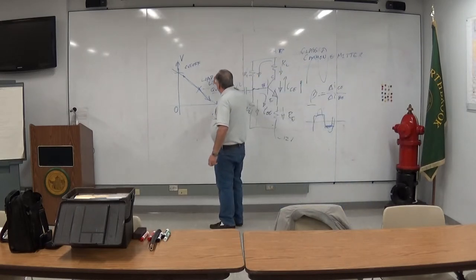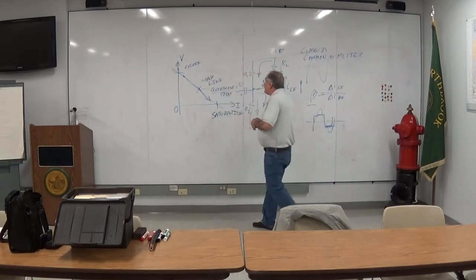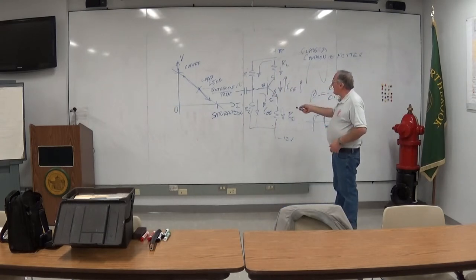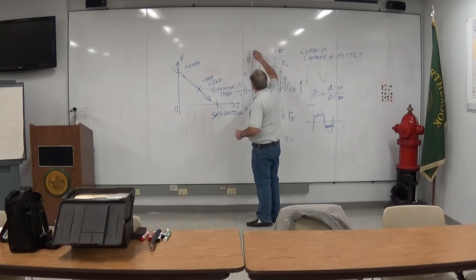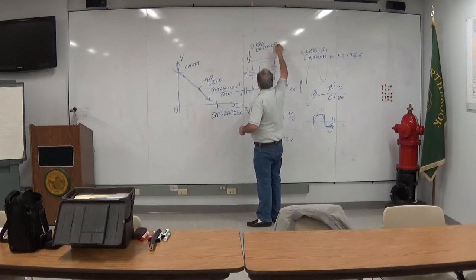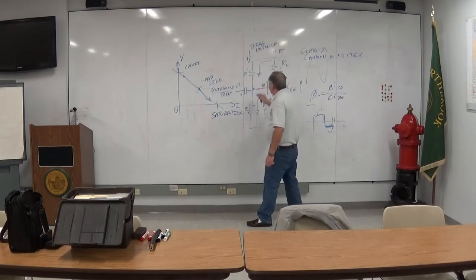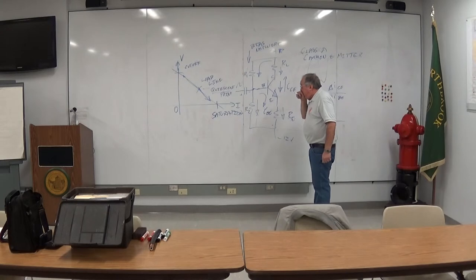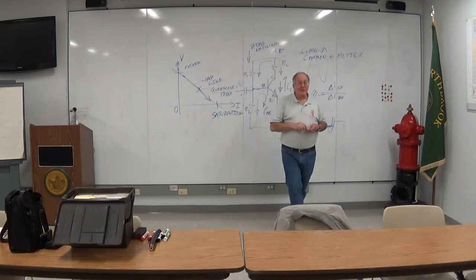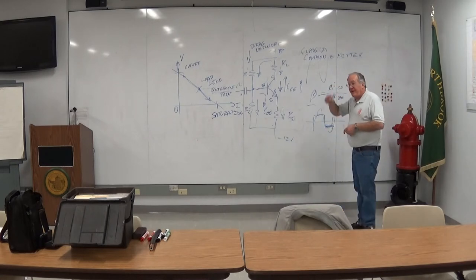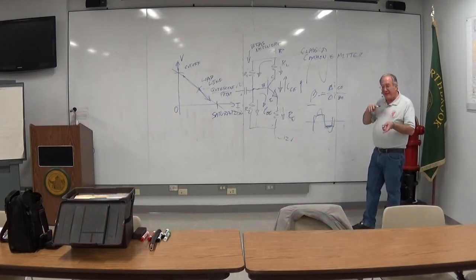That's the transistor lesson here. This is how they work. This is what they look like. And these guys here are your bias network. That is your resistors that set up a condition so that you'll be roughly here when there's no signal coming in. And then you can slide up and down the load line when the AC, the signal you're trying to amplify, shows up.